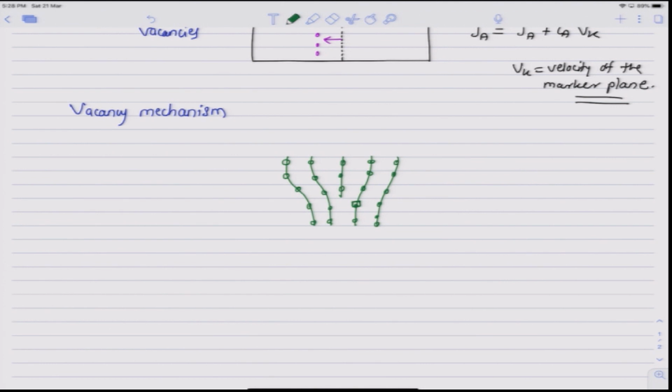In the presence of an excess of vacancies, they will be transported to the nearest dislocation, and when a vacancy comes near the dislocation line, it will jump into the dislocation line and an atom will make a reverse jump. This way a vacancy will be introduced into the dislocation and the atom will be introduced from this extra half plane into the bulk of the crystal.